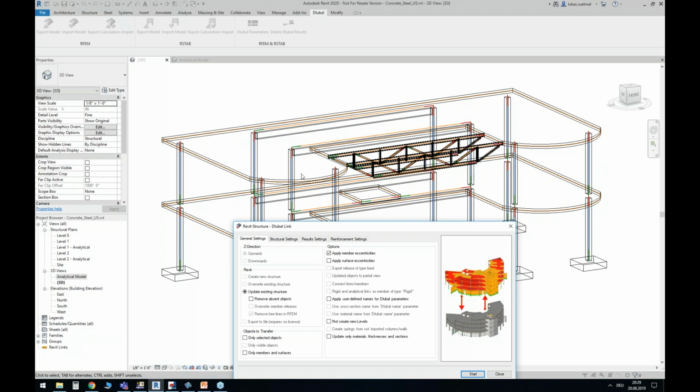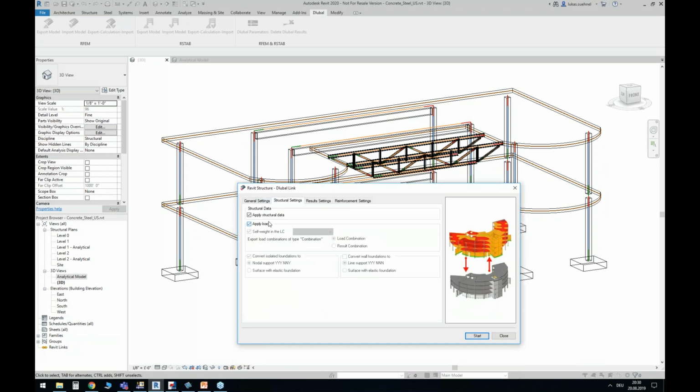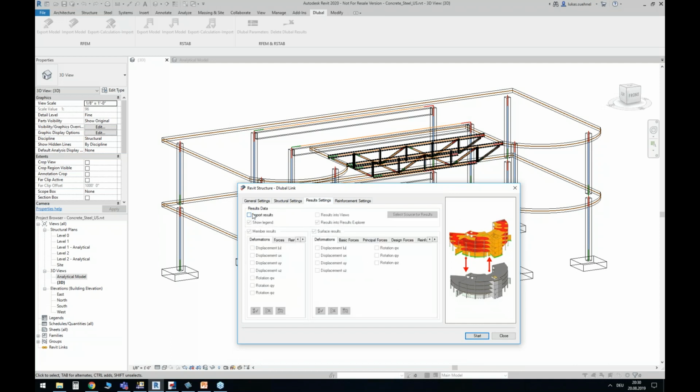Apart from that, I will change with this update the thickness. I can change the cross sections. I will add new beams here and so on. And I can also update my loads if I would have any changes. And additional to that, I can also import results. For example, for the members, I could import the axial forces that I've just displayed beforehand. And for surfaces, I can also import, for example, the required reinforcements that I calculated in the concrete module.